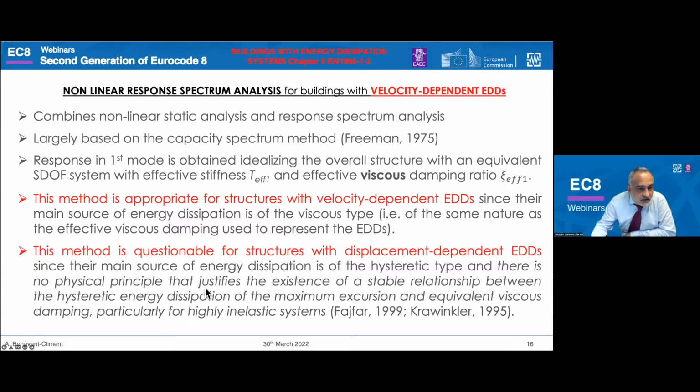Well, this is a controversial issue that has been largely discussed in the literature. And it is one of the reasons why, for buildings with displacement-dependent devices, the more straightforward approach of the energy balance based method has been adopted instead of the method used for the velocity-dependent dampers.